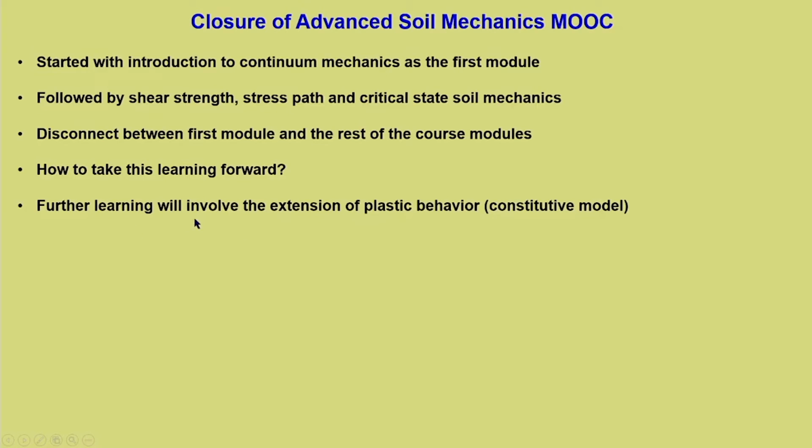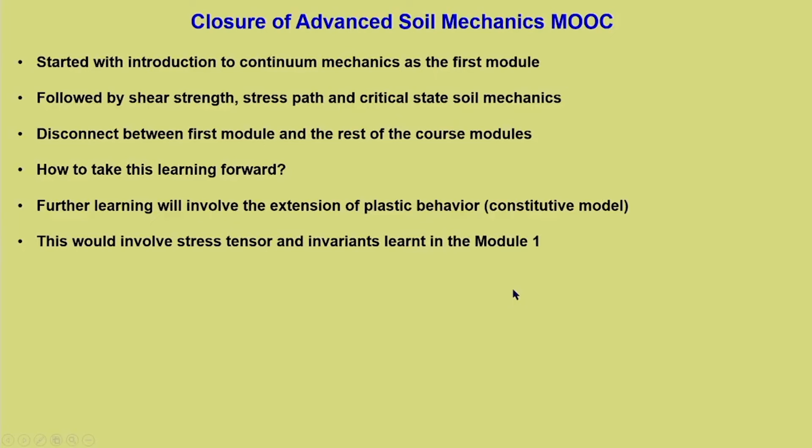Now further learning will involve the extension of plastic behavior, more into constitutive modeling, and not only cam clay, there are various other plastic behavior and the fundamentals of plastic models of geomechanical behavior, wherein we also have to learn more about non-associated flow rule, definition of plastic potential, and how do we use this for solving a problem. In fact, this part we have not touched upon.